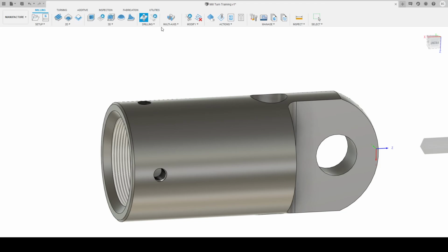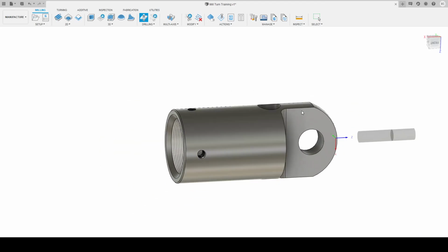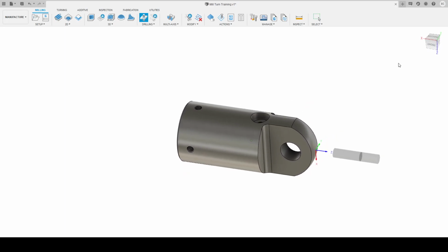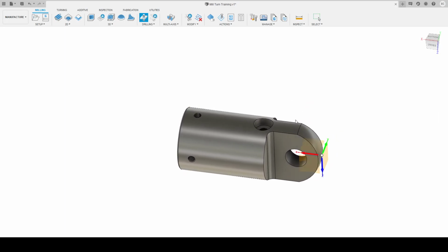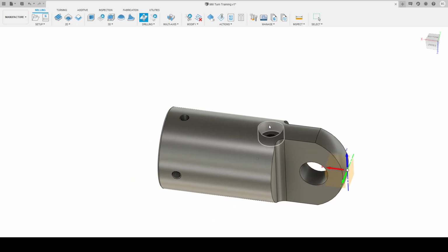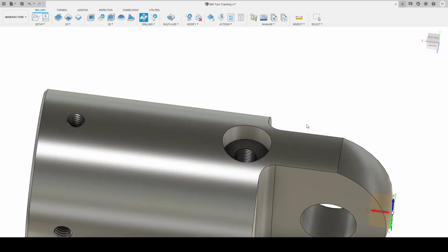And then our cutting data, how fast you want to tap. So we'll go about 6 meters a minute, which is pretty right. And then we'll go accept. Okay, so we actually have a tap that's 10 mil diameter and 0.907 thread pitch, which is right for a 1/8 BSP. We can go into our geometry, orientate our tool that way, and then the hole faces that we want to tap,